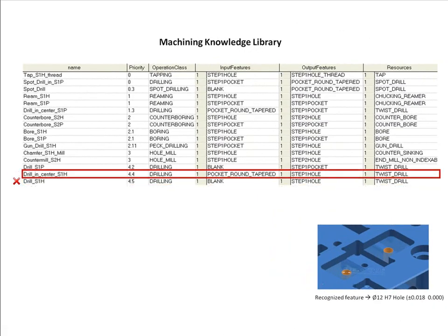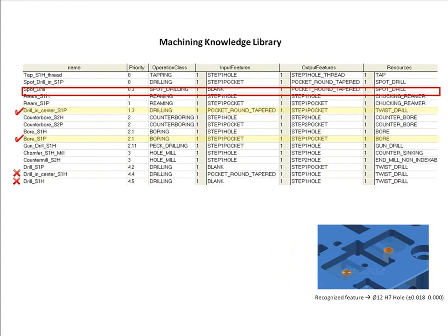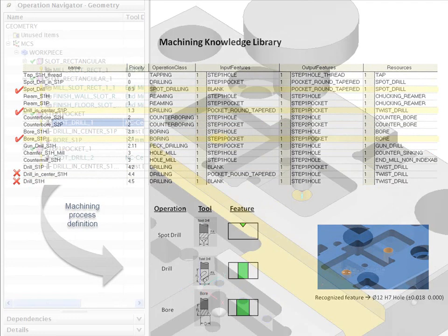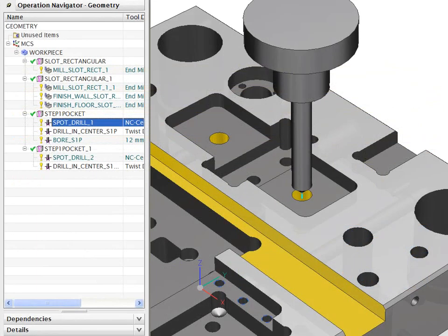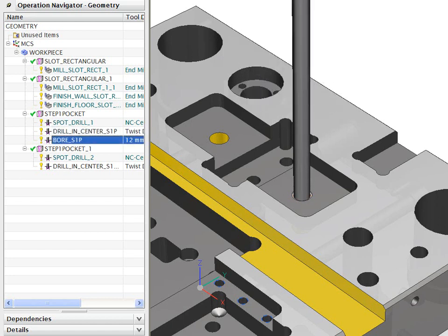As we have seen, the feature-based machining in NX Cam uses a special approach to generate the machining process for each feature from a library of standard operations. This generative approach avoids the need to build and manage a complex set of machining templates, as seen in many systems. In addition, the system allows us to use PMI 3D model data to drive automated NC programming.